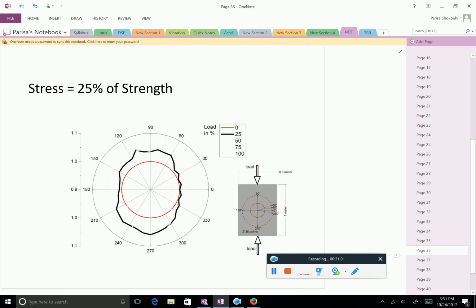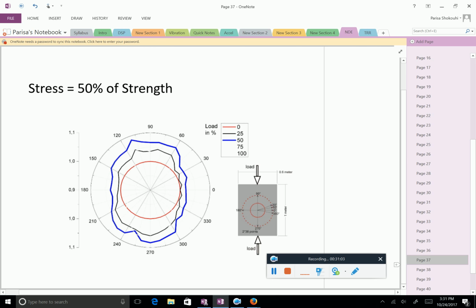It's every 10 degrees curve. And as you increase the load, the velocity still increases. And you can very easily see what I told you about direction dependency, because here is maximum, and then as you go here, it becomes minimum. And well, of course, concrete is very heterogeneous, so you don't get a perfect ellipse, but it is real data, so this is what we got.